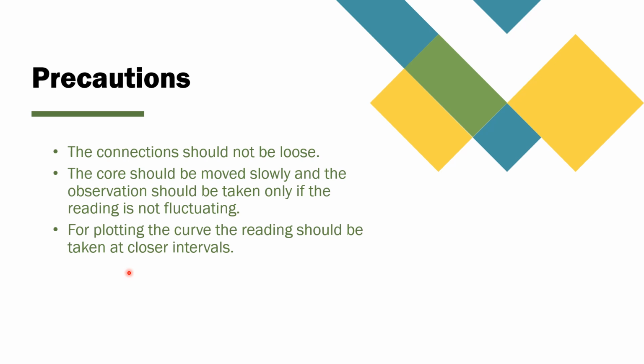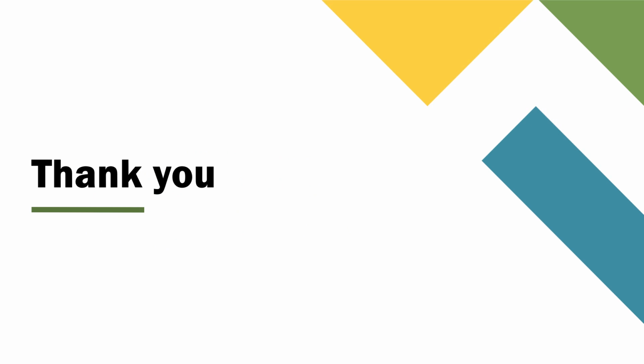Finally, coming to the precautions. Here are some precautions that you should take while doing the LVDT experiment. The connections, the wires, should not be loose. And while taking the observation, the core must be moved slowly, and the reading should be taken when it is not fluctuating. And for plotting a good curve, the readings should be taken at closer intervals. So this is how we perform the LVDT experiment.